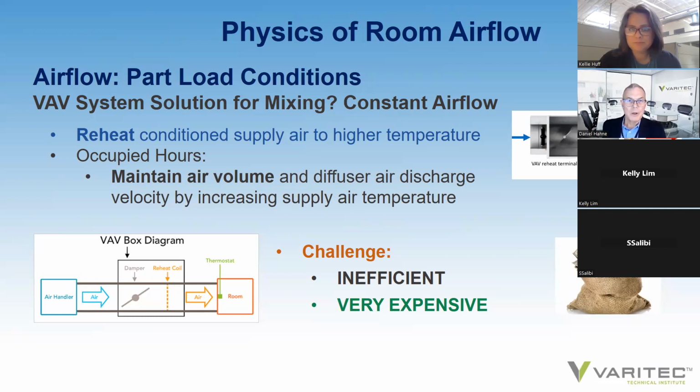Absolutely. It is well known in the industry, and it really reached a focus during the pandemic, how properly humidified environments between 40 to 60% RH are more effective at reducing the risk of infection than drier environments. And when is our driest time of the year? November, December, January. So absolutely, humidification in a displacement ventilation project is certainly doable, providing the owner is confident they can control the humidity in the space.